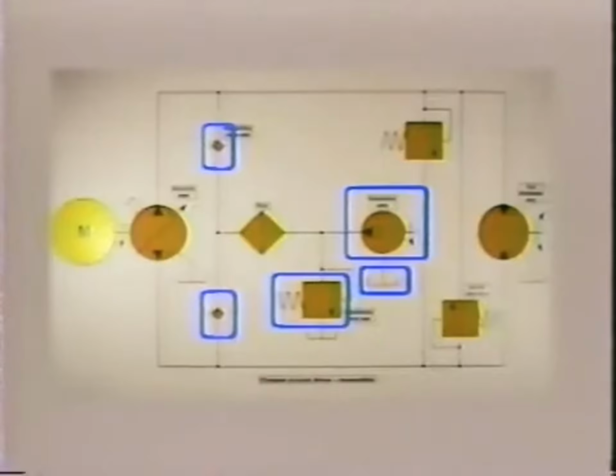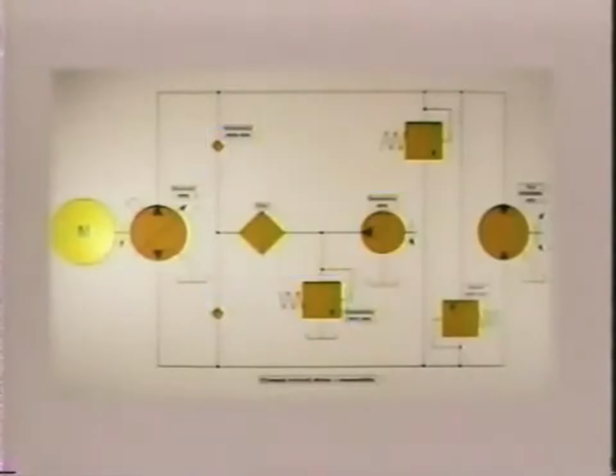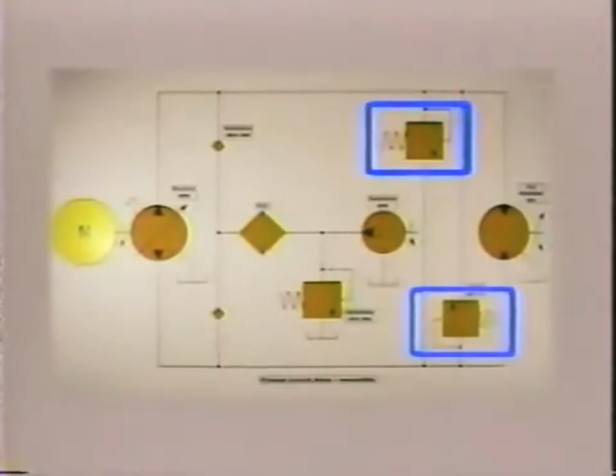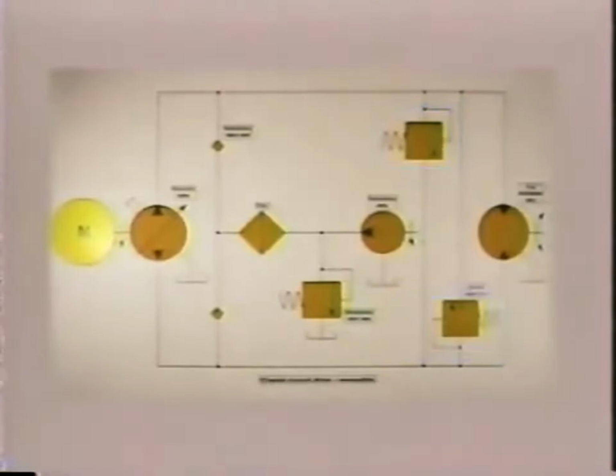This not only enables us to have a more responsive system, but sometimes permits the pump to be driven at higher than normal speeds. Of course, there's always the possibility of the motor being overloaded or stalled, so we must have overload protection. This is accomplished by installing cross-line relief valves, which open and divert pump flow back to its inlet during overload conditions. But remember, oil going over a relief valve is energy being wasted, and wasted energy generates heat, and there's no way in our closed loop to dissipate it. So stalling for extended periods must be avoided.